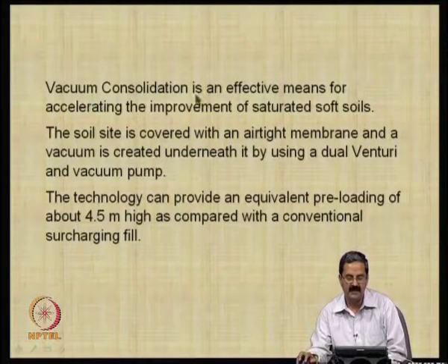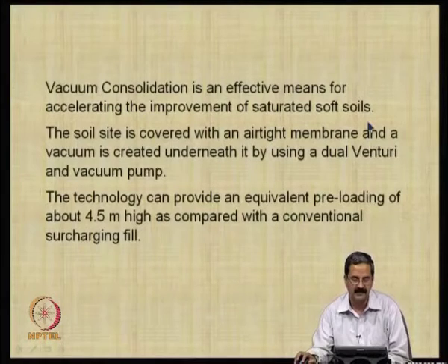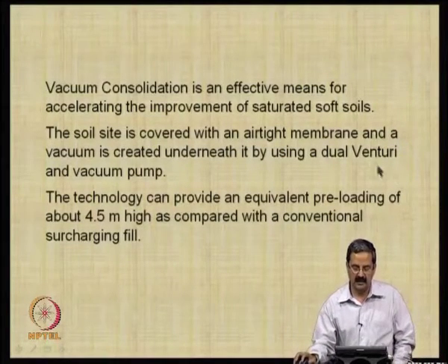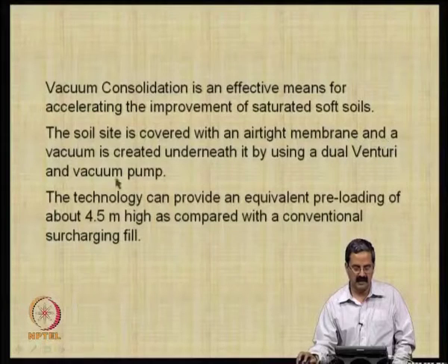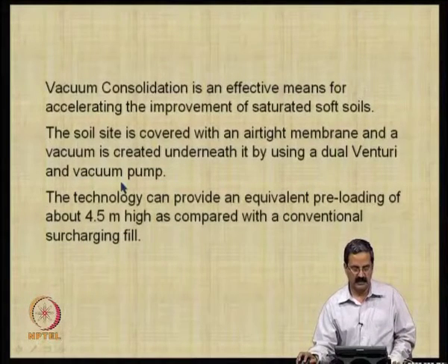It is an effective means of accelerating the improvement of saturated soft soils. The soil site is completely covered with an airtight membrane, and a vacuum is created underneath it by using a dual Venturi vacuum pump. There is a pumping system here.